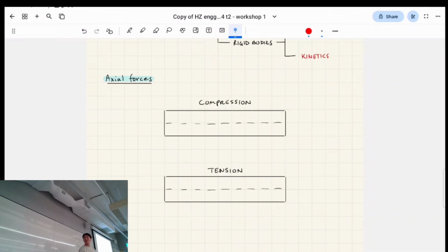Another example, there's not really one in this room, but pretend there was a big column in the middle of the room, from the floor to the ceiling. It's taking gravity loads, so that's all in the vertical direction. And it's actually going to be compressed. That column would be in compression. Like the projector, there's some sort of steel member holding up that projector. The projector's heavy, so that's in tension. It's being pulled. You should try to get a good holistic understanding of these two concepts because it's the foundation of what we're going to be talking about next.